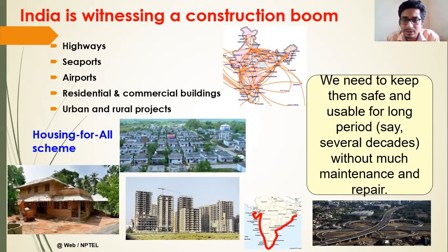In a lot of cases, we will see later in the upcoming slides, a structure may need mandatory repair work, because you cannot find any concrete without cracks. Wherever there is concrete, it will experience a crack. It may be after one month, after the elastic shortening, or after several decades.